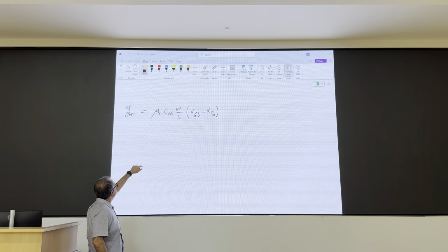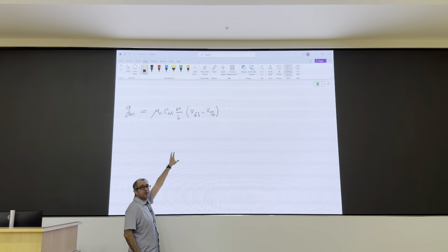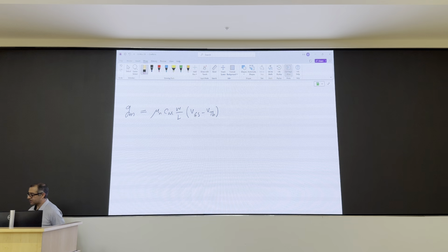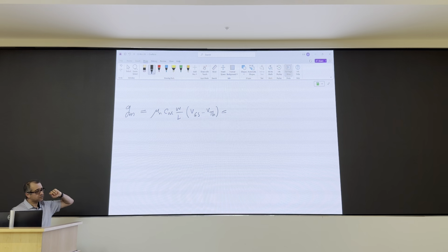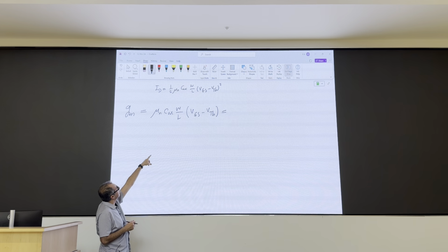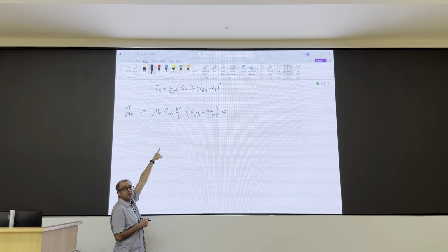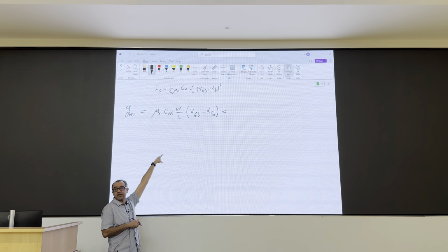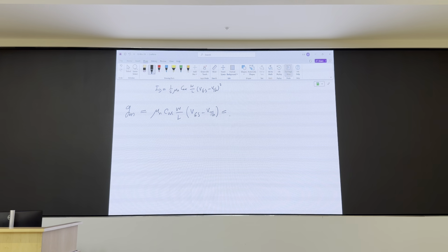power, right? For MOSFETs, well, this is a little bit of good news. Actually, let me expand this. Let me write this as this other alternative formula. I'm going to multiply this thing. So remember, what was the ID formula? ID was 1/2 mu n Cox W/L times VGS minus VTH squared. Right? And look at this formula at the bottom. If I multiply the one at the top by 2 mu n Cox W/L, I have the bottom one squared, right? Or I can find GM from this expression.